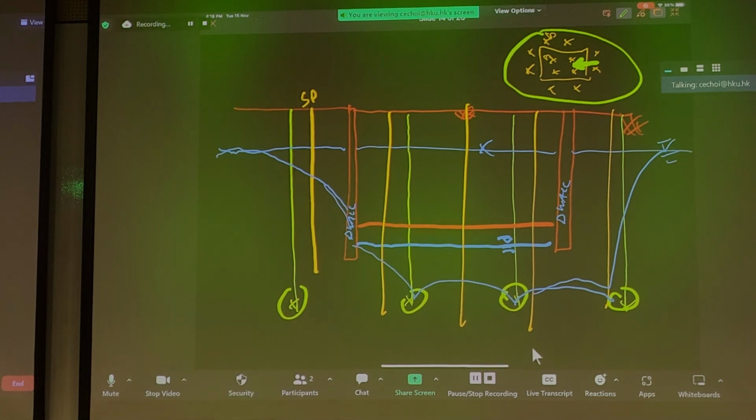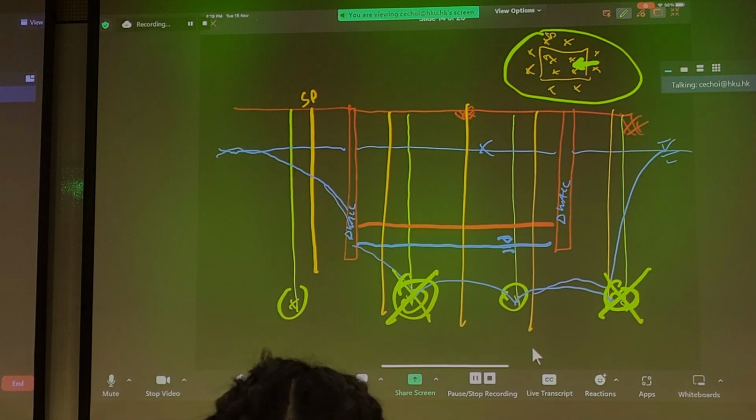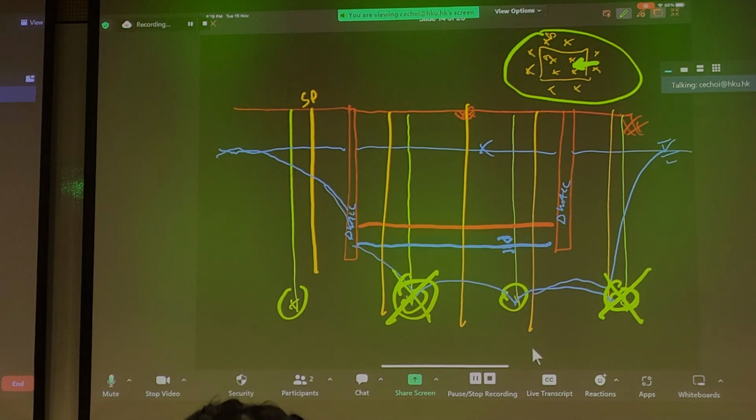So the pumping test has functions. The first function is to make sure you can draw down to the safe working elevation. The second function is, what happens if this malfunctions, what's the recharge rate? It's common for pumps to malfunction. Will your entire cofferdam recharge too quickly so that whoever's working inside doesn't have time to evacuate? So there's main functions, remember that.